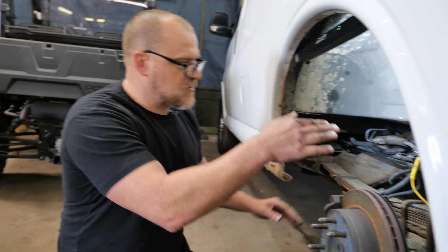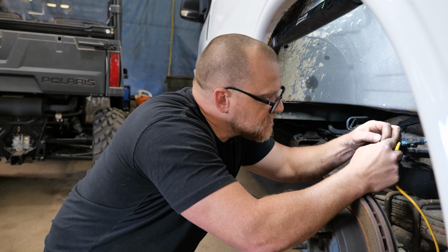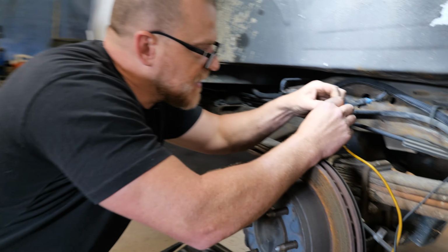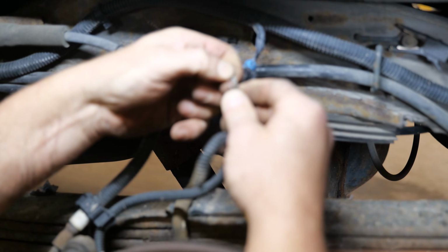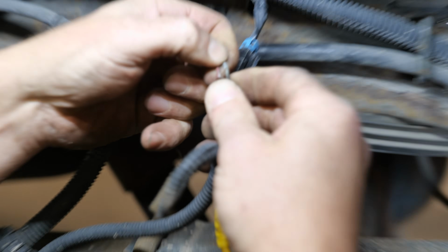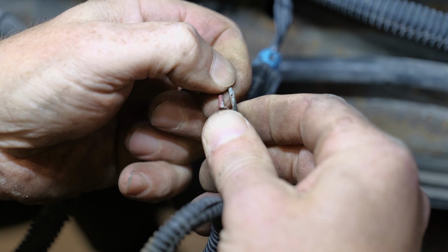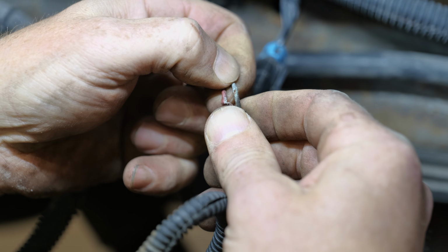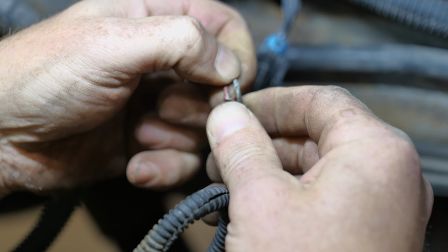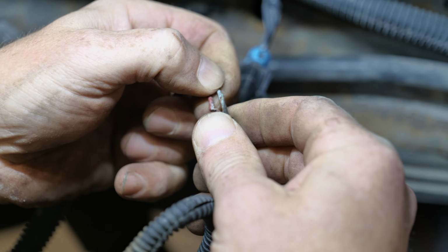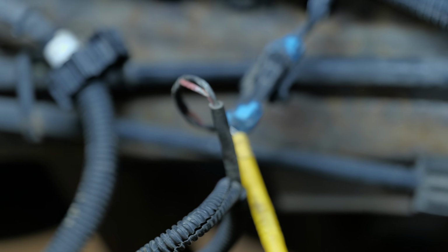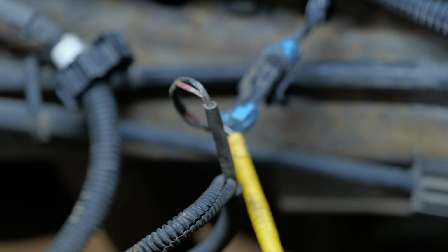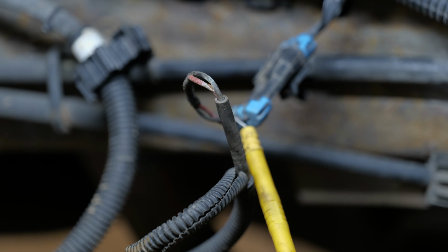To be clear about this ground wire, because I said it has some damage too: it does have damage, but it's not damaged at a point where they're all completely open. That ground is still intact. There's still a couple of strands left on that ground. So we weren't having a voltage drop there yet, but we were going to. But it was the signal side. And this is not an active or digital speed sensor. It's just an analog one.